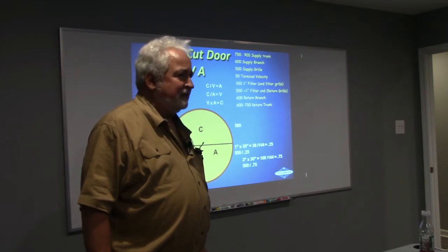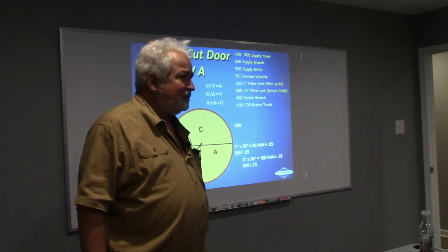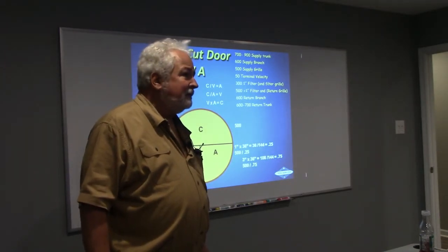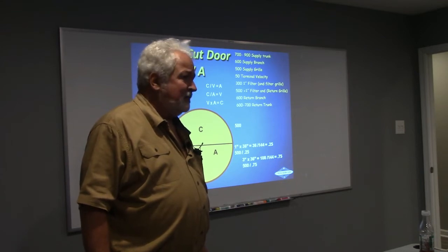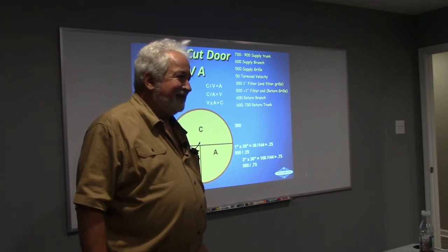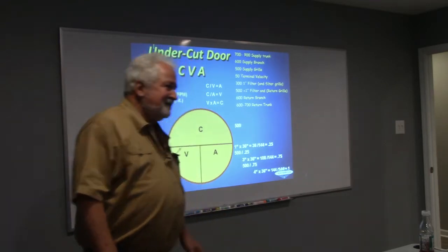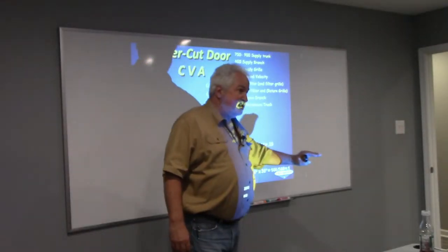So it's still noisy. You think that room is still being pressurized because it's trying to get underneath that door? Yes, I think it is. We cut 3 inches off the bottom of that door. What are we gonna have to do now? Looks like a mobile home everywhere. You're gonna have to do it back. We're gonna cut off 4 inches. We're gonna be right there at the hinge now, all right?